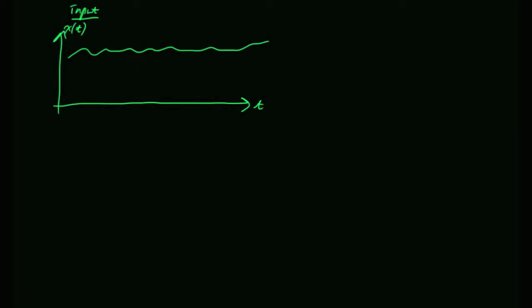Like this is an impulse, and this is an impulse, and this is an impulse, and so on. Isn't that right? So, if I want to know my system's response to this arbitrary signal x of t, all I need to do is find the impulse response for each of those impulses and add them up.